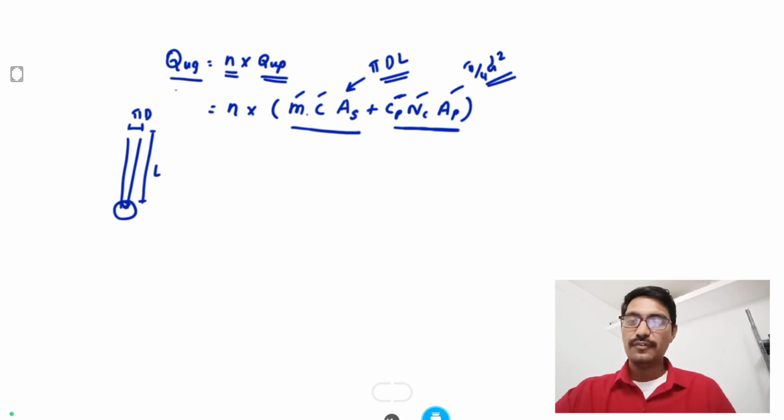Okay, the static formula is mainly based on static piles, that is non-displacement piles, which are the cast in situ piles. If we go for the dynamic formula, we can use the Engineering News formula and Hiley's formula. Those formulas are used for driven piles.